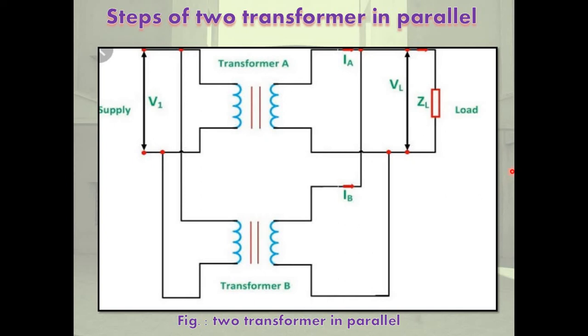Next is measure the voltage between the secondary terminal of the transformer and the corresponding bus bar. Voltage between terminal B and bus bar Y, terminal C and bus bar B. If these voltages are 0, make permanent connections. If these voltages are twice the phase value, cross connect as follows after measurement as 0. B of transformer Y to bus bar B, C of transformer Y to bus bar Y.